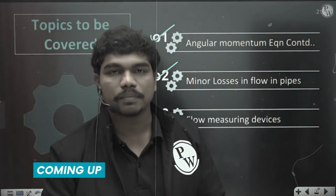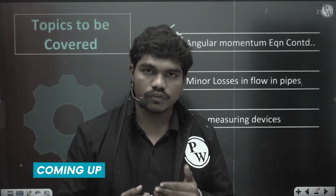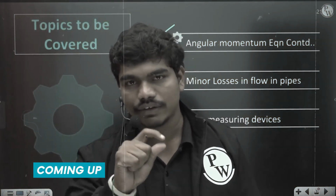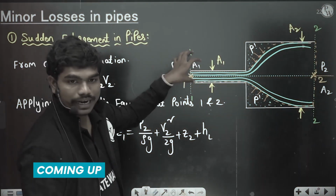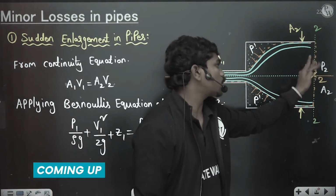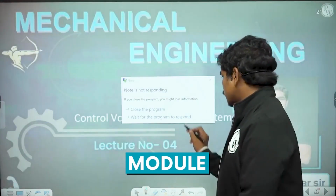What is control volume, what is system. We have seen what is Reynolds transport theorem. We have applied this Reynolds transport theorem. Normally the main reason for the pressure drop in the pipe is actually because of the friction between the pipe material and the fluid. Suddenly, let us suppose if fluid starts entering the small pipe for some exit to the pipe, then the fluid suffers some loss. Total energy of the fluid at this location should be equal to the losses that happened plus the total energy available at this location. This is the fourth lecture of this module, control volume analysis.